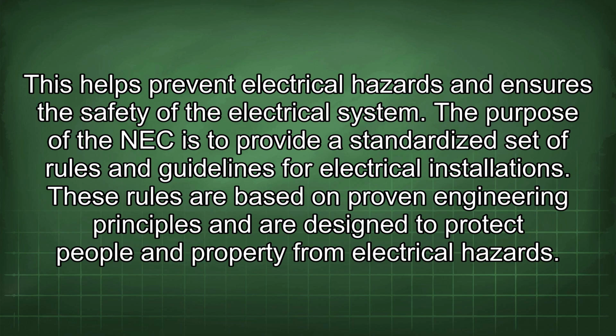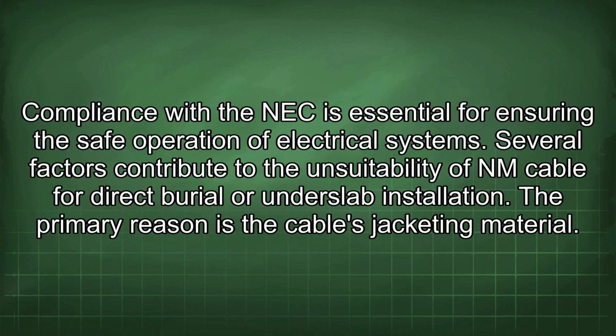The purpose of the NEC is to provide a standardized set of rules and guidelines for electrical installations. These rules are based on proven engineering principles and are designed to protect people and property from electrical hazards. Compliance with the NEC is essential for ensuring the safe operation of electrical systems. Several factors contribute to the unsuitability of NM cable for direct burial or underslab installation.